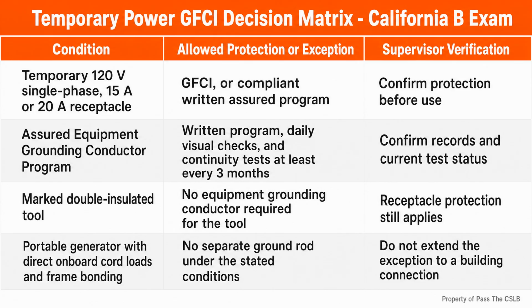The concrete crew may see a reinforcement tying task. The electrical contractor sees an electrode connection. I have to coordinate both scopes before the concrete truck arrives. Consider a hypothetical foundation pour. The reinforcing steel is installed, the forms are ready, and the electrical contractor has not completed the concrete-encased electrode connection.